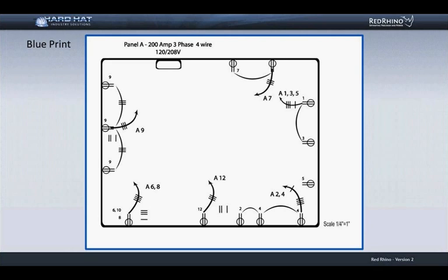Again, I roll the scale X over the path of the conduit at a right angle and overroll slightly to cover the conduit riser. This time I'm going to say that the total run length of half-inch conduit, and I'll roll those both off with 4 number 12 wires, is 210 feet long. Next, I write the information on the takeoff sheet.